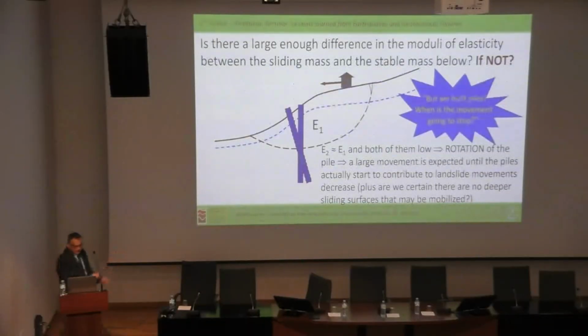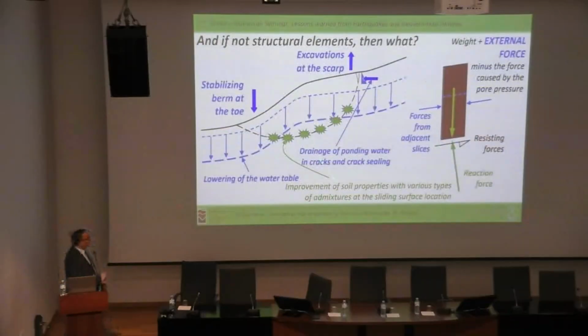And if not structural elements, then what? Excavations at the scarp, stabilizing berms at the top, lowering of the water table, or even trying to improve the properties of the soil along the sliding surface.